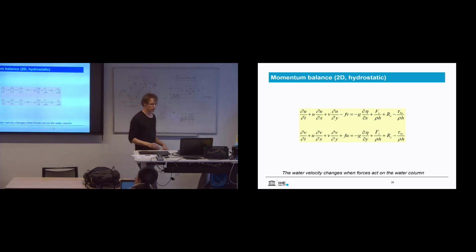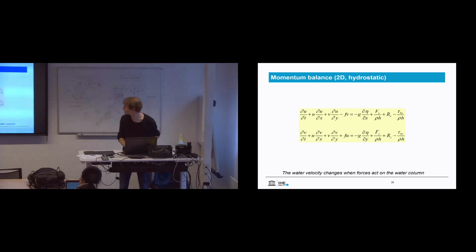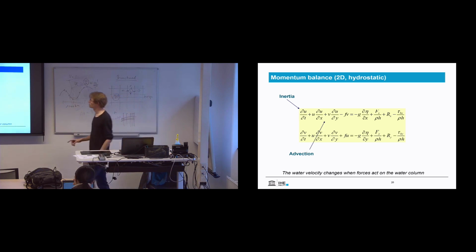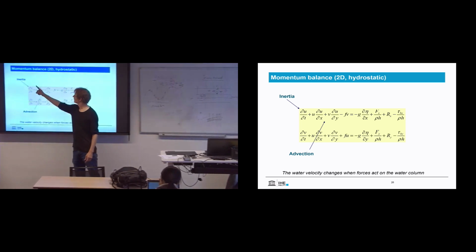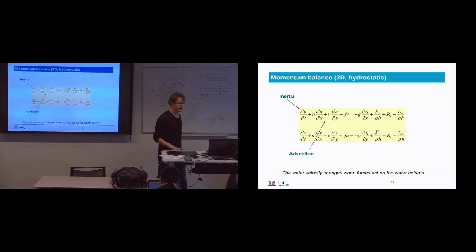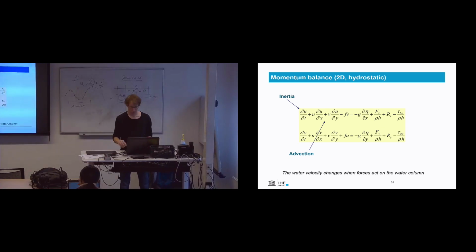So this has different terms. The inertia is the first one, so that's basically the change of velocity in time. Then you have the advection term, and these two are the total Lagrangian velocity change. So this is a Eulerian representation of the equations.